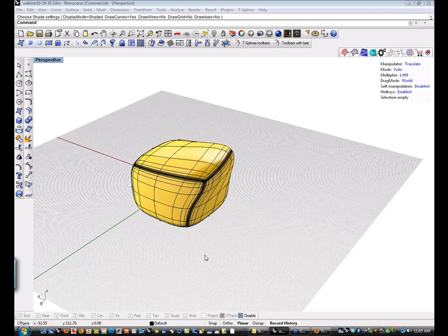Does T-splines and Rhino benefit much from a dedicated FX range video card, or would a good gaming card be as good? I actually had just been through that gauntlet myself as far as upgrading equipment, and spent a lot of time talking to Jeff Lesor at Rhino. A good gaming card will work really, really good with Rhino. The problem with gaming cards is that I use a bunch of other software, and one of them is Freeform by Sensible, and they're really fussy about having a Quadro level video card. It just flat out will not work unless you have a Quadro card.